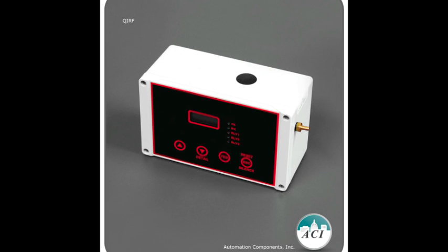So if you're getting involved with a mechanical room and you come in and realize it's an R12 freon and you had ordered an R410A, right from the front keypad, you can select R12 and it learns it, so you don't have to go back to Stromquist or back to your plant or office and pick up a new one. You can actually choose it right from the front drop-down menu. And it learns that, and it's factory calibrated. It's a program right on the chip.